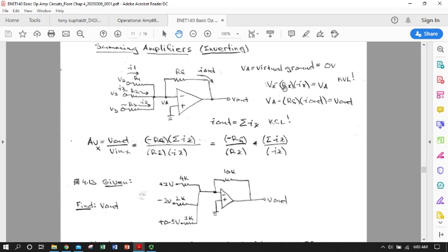We take R sub x, I sub x to the other side, and we have an expression for the input independent of any voltage here at VA because it's 0. So we have negative RF times the total current output, which is the sum of the inputs, divided by any one of the input resistors, the resistor for whose branch we're looking for the gain, divided by its current.